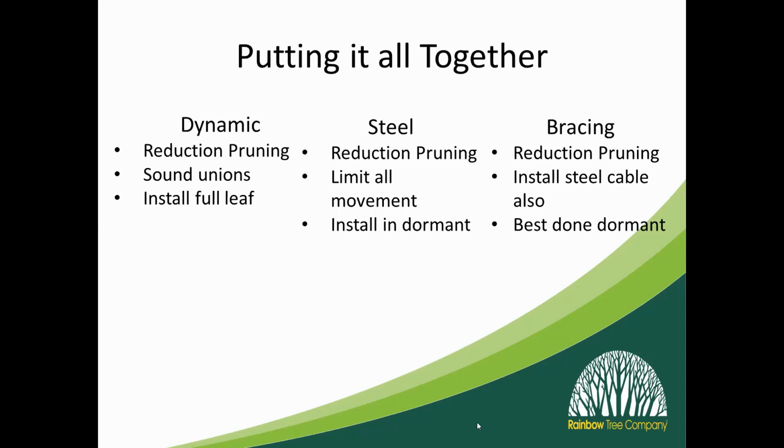But if you do have an active split, a cable itself, if it's still actively splitting, might stop it from splitting, but it could shear off. So if it's opened up, say after a storm, with a couple of inches open, that's where I'd start doing bracing if we want to save that. And only if the client is aware that this is not 100% going to save it, because they can shear off.